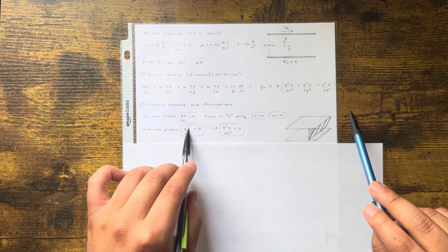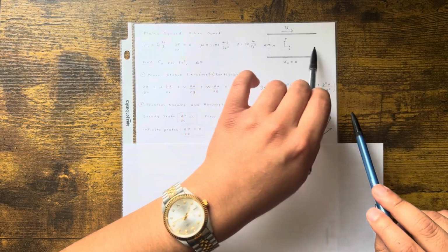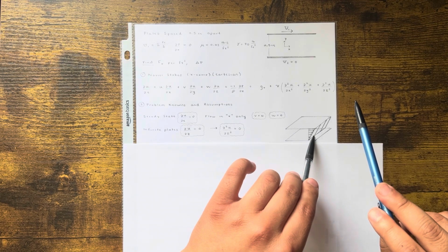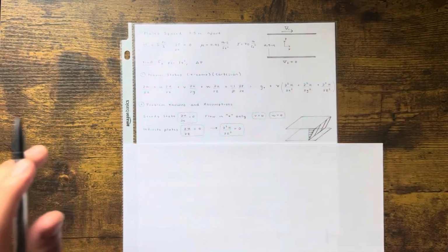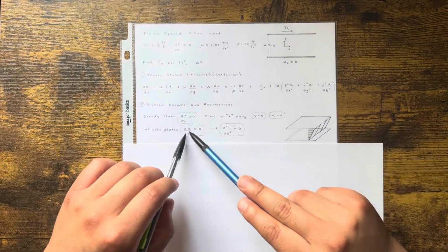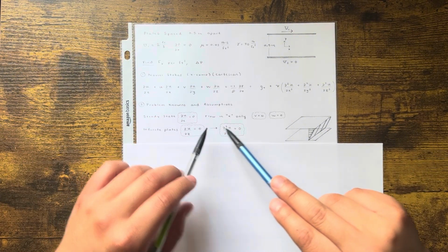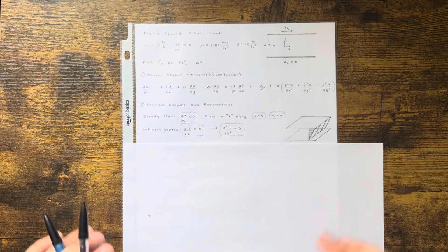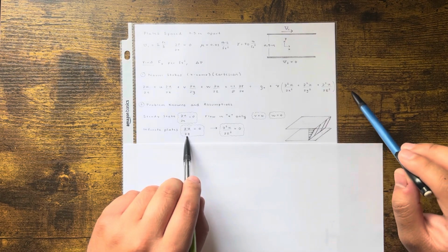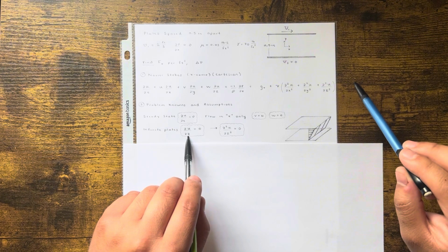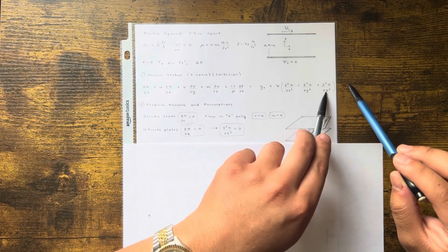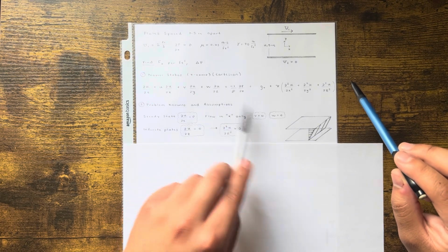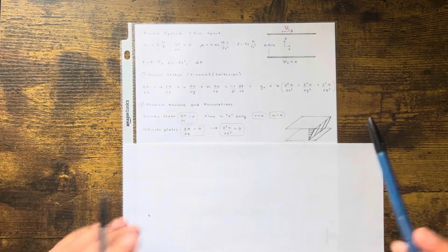The change in u, which is the velocity in the x direction, does not change with z. So it's the same here, here, and here, all the way into the plates. So the change of u over the change in z is 0. Take another derivative of 0, that's another 0. That's all that happened there. So that's good, because we canceled out this term, delta u over delta z. This one right here is the important one because we canceled this out. That delta u over delta z also got canceled, but w was already canceled, so we didn't really gain much there.